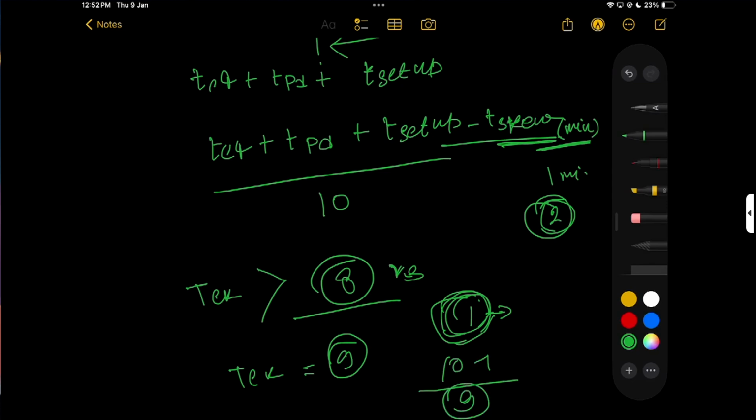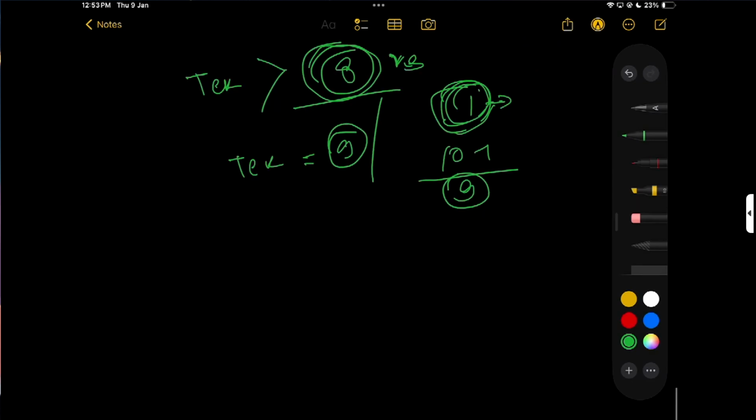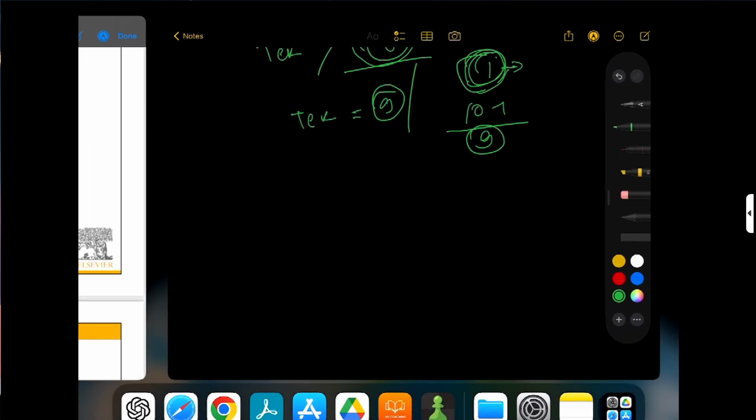But we assumed that our T clock is 8, so it will be violated, and some mismatch will happen. Then my T setup and T hold conditions will be violated, and it again goes to the metastability position. We don't want that, unnecessary metastability conditions we created. So I hope this T skew condition is understandable.